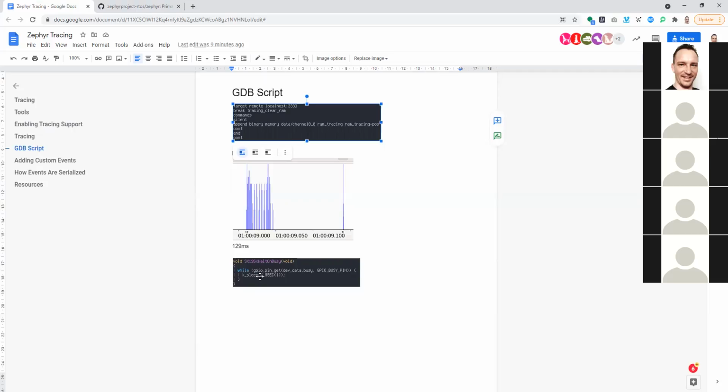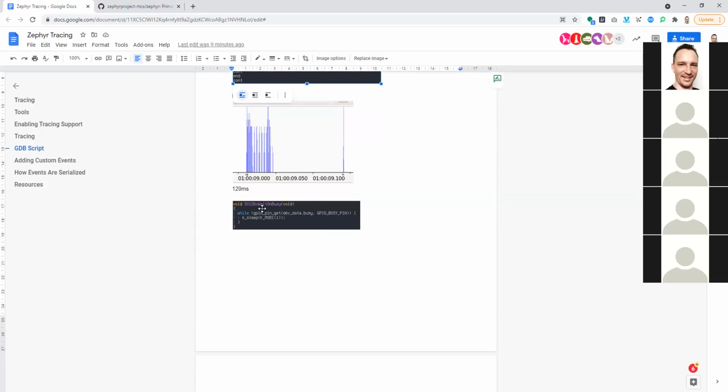And this is typical kind of crap that you find in code that comes from Arduino libraries, because this should have been implemented using a semaphore that is given from an interrupt, and then this should sleep on a semaphore, not loop in a loop like this. But this is actually not the culprit. This is not what is generating this pause here.